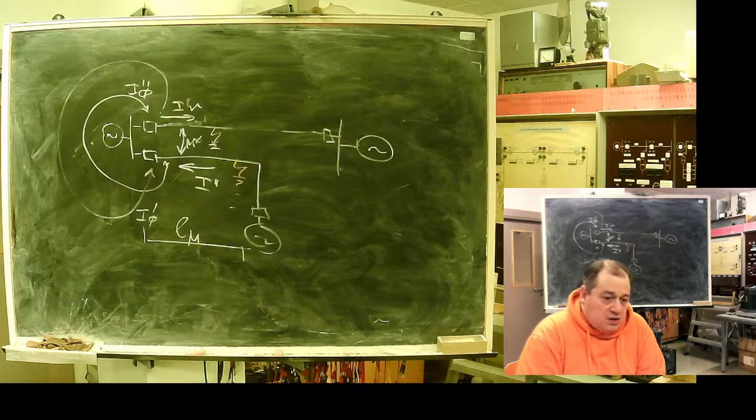First, good relays are equipped with a filter preventing influence from higher harmonics. And for a modern relay, it's good to have a safety check. If you have a high presence of fifth, seventh harmonics, the relay characteristic should be switched to less sensitive or delayed to prevent false operation from this inrush current.